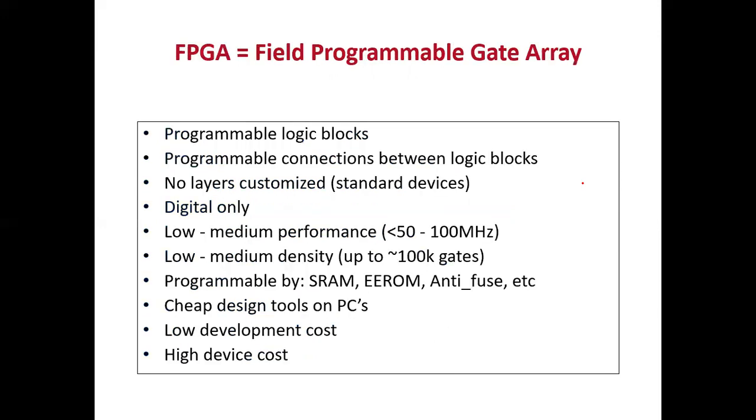The part of the gate array is FPGA, field programmable gate array. Programmable logic blocks are there, with programmable connections between the logic blocks. No layer is customized, it is a standard device. Digital, used for digital only. Low to medium performance, low to medium density.